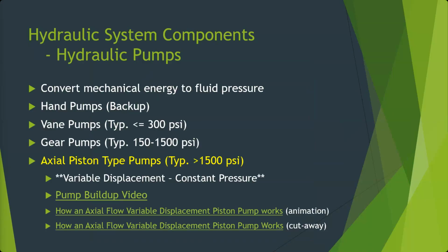Same thing there. So remember, our hydraulic pumps are taking that mechanical energy and creating fluid pressure through it. Those are getting that mechanical energy from somewhere else, whether it be an electric motor that's getting its power from a generator, that's getting its power from a mechanical source, that's getting its power from fuel, or directly from that mechanical gearbox on the engine that's getting its power from burning fuel. Okay. So we're going to convert energy to fluid pressure. Some of the pumps you'll see, hand pumps. We'll have a few of these on some, but not all transport aircraft, used as a backup or an emergency.